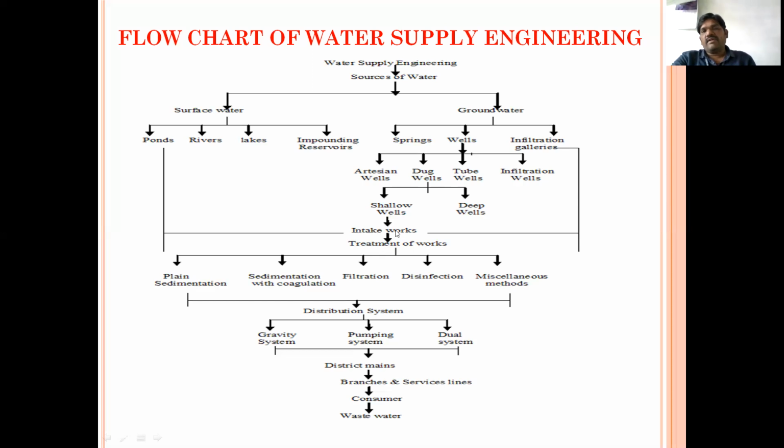From the intake works, the water will be collected. After the collection, the treatment will be done. In the treatment, we may observe plain sedimentation and sedimentation with coagulation, followed by filtration, disinfection, and all other miscellaneous methods to remove the particles which may not be removed in the previous methods.